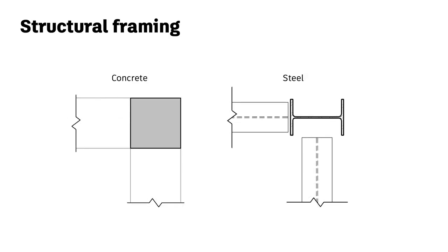This property is called the model behaviour, and it is set in the Revit family parameters. In the example shown, a concrete frame will join and become monolithic, but other concrete members such as precast, steel or timber will have a gap between the elements.